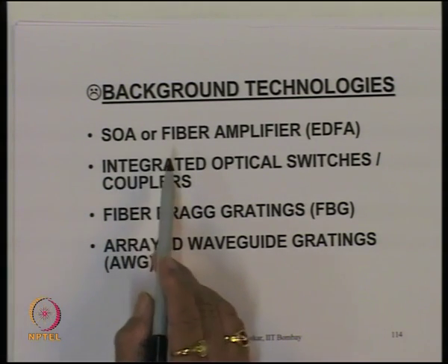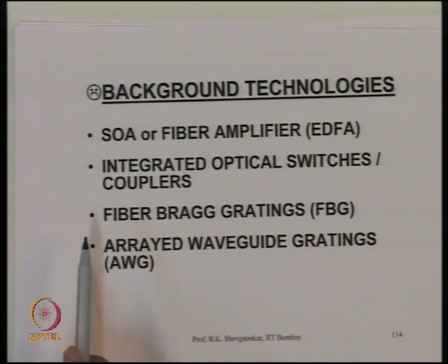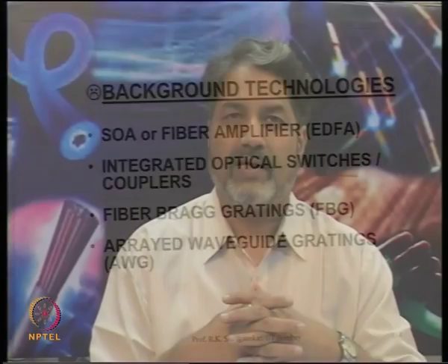In the last two lectures we investigated optical amplifiers, and in detail we saw one of them, the EDFA. We saw that if we take the normal fiber and dope its core with erbium, we create energy levels such that we can amplify light in the wavelength band of 1550 nanometer. Typically we get a bandwidth of about 30 nanometer in that band, so about 30 to 40 WDM channels can be amplified in one shot by this device.